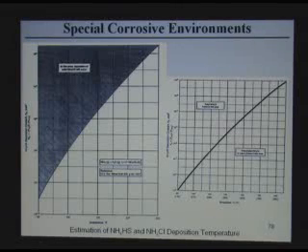These are very old data on ammonium bisulfide deposition, as to when it should deposit. This is the temperature and the ammonium concentration. I think if you are below this curve, you are depositing. If you are above this curve, it is in the vapor phase. The same thing applies for ammonium chloride. The chloride dew point is much higher than the ammonium bisulfide, so ammonium chloride starts first, even upstream of this heat exchanger. The ammonium chloride corrosion happens there, but also in the air cooler, as well as the ammonium bisulfide.